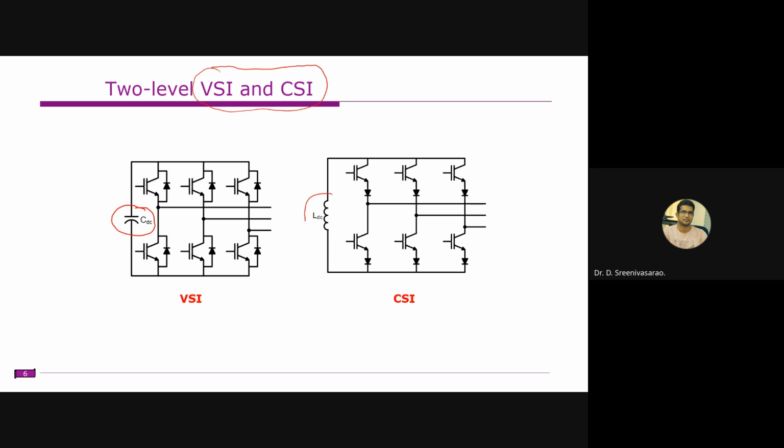So we can obtain this DC voltage source easily. Whereas in this case, we need to keep the current constant, right? This kind of current source is not readily available. The only way is to connect some DC source with a large inductor, so that will form a current source, right? That is one of the drawbacks. We need to connect a large inductor, and the size of the inductor makes it heavy, and the circuit is also bulky, and it will also produce more losses in the circuit.